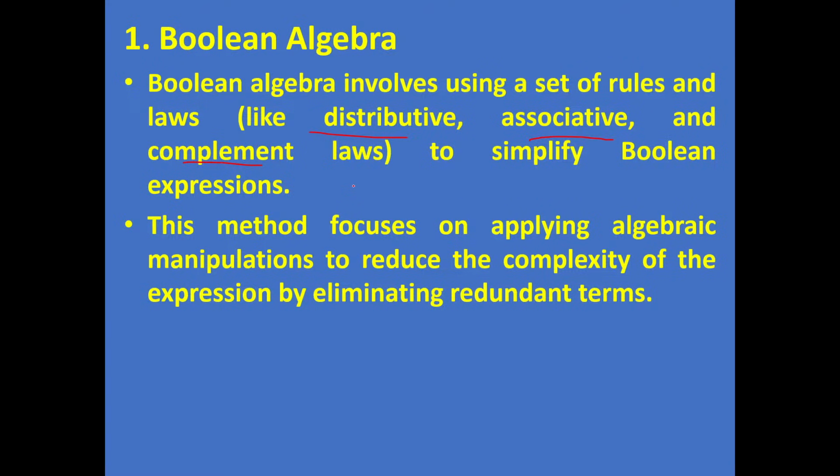If a circuit is designed using logic gates, for that circuit you can write a Boolean expression and later you can follow these Boolean rules or laws to get a minimized circuit. For that minimized circuit, once again you can draw a simplified logic circuit diagram.